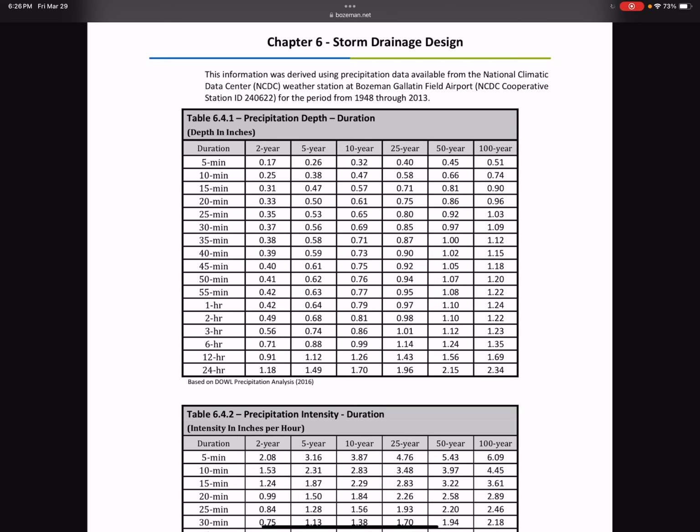So from a 30 pounds per square foot value, we're looking at 6 inches of water on our roof, right? And so this being 1 inch, it kind of shows that we are designing for quite a bit more load on our structure. And there's actually an equation to take that intensity, and then you look at essentially the static head that is required to drive that much water off the roof through your secondary drain.